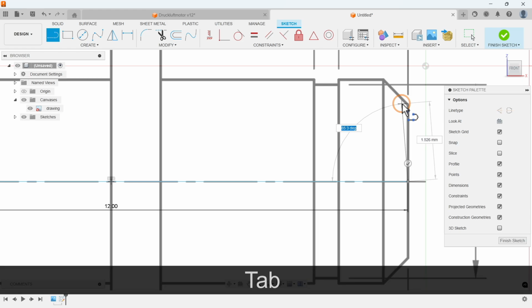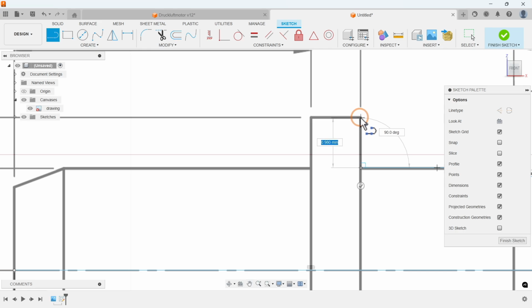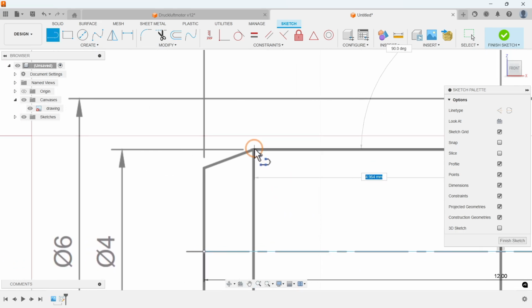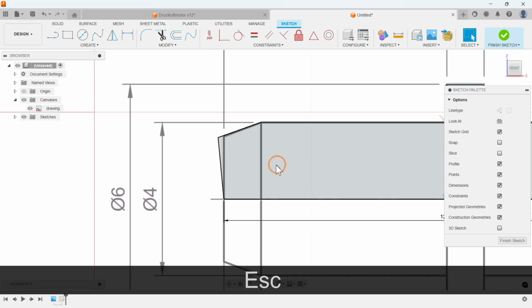You can set the angle either by entering 90 degrees or by using the blue dependency symbol. Now, draw the rough contour of the crank pin. Dependencies are automatically created in the process. If one is missing, we will add it manually later. Make sure the contour is closed at the end. You'll see it in the rectangular symbol. It's not a problem if the line isn't perfectly vertical.